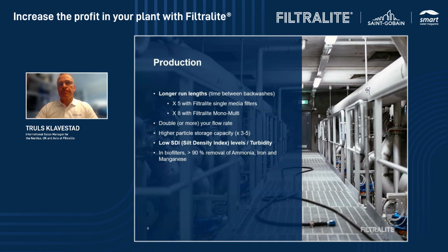And iron, we can increase that, and we can reduce that very down to a non-detectable level. So if you are around 2-3 ppm of iron, you can come down to 0.001 or nearly close to zero with the right condition. That goes quite fast to build up the right bacteria for iron removal.